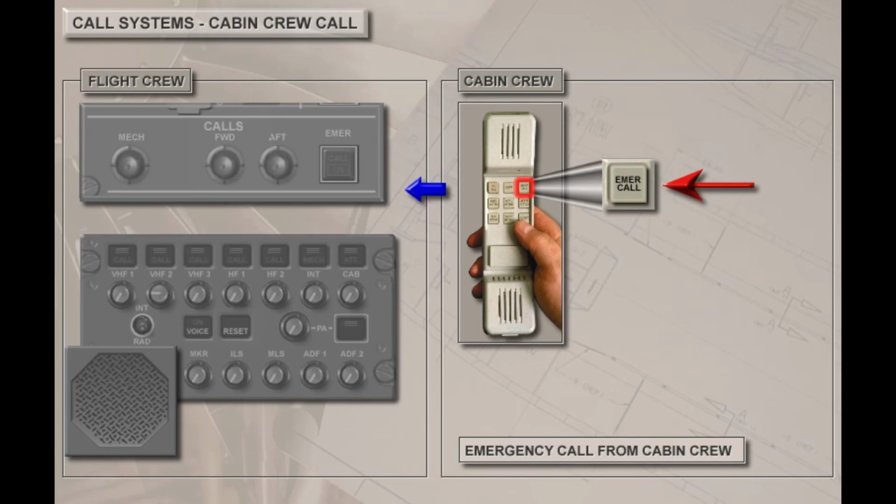Interphone communications are established by the pilot selecting the attendant audio control panel transmission key and then responding by depressing the press-to-talk switch on the audio control panel or side stick. It is of paramount importance to realize that you cannot hear the flight attendants until the cockpit microphone has been keyed, at least momentarily. Touch the emergency call push button to call the cockpit.